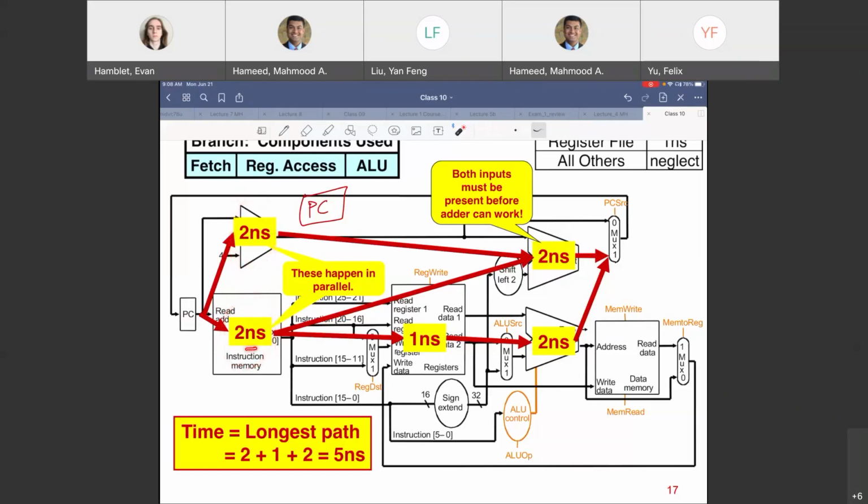Next, you know the 16-bit immediate, right? From the instruction memory, you know the last 16 bits of that field. That is going to be your immediate constant. Sign extender, we are not associating any delay with that. Negligible delay there, negligible delay with shift by 2. So our number to be added to PC plus 4, the branch address, is ready already, right?